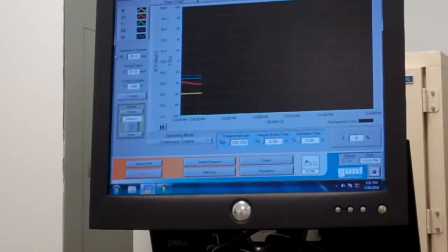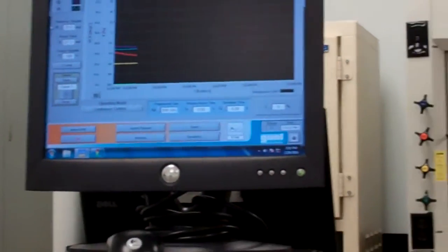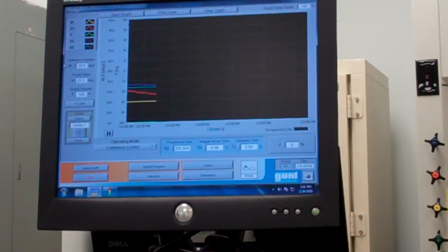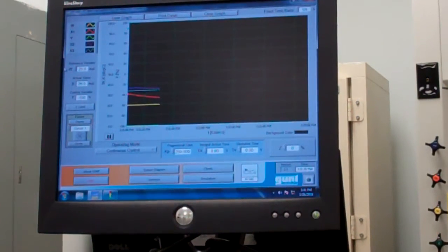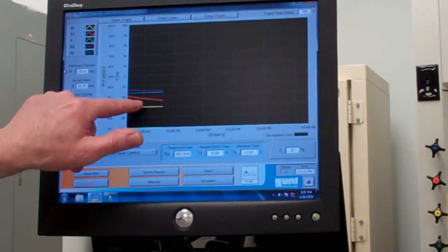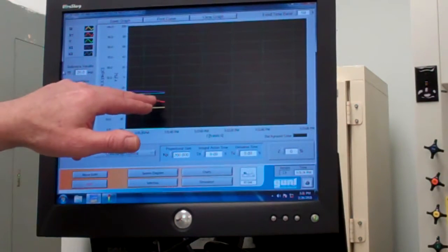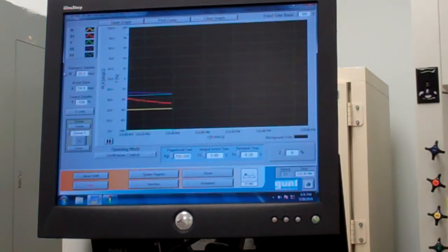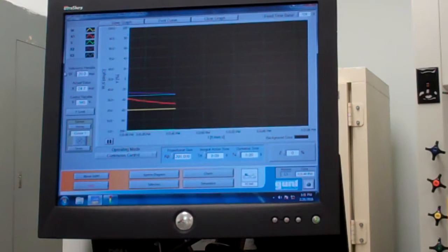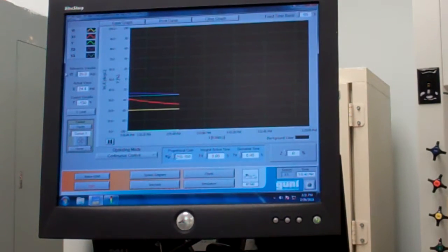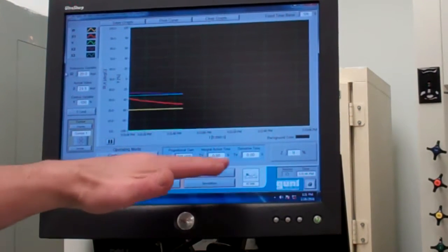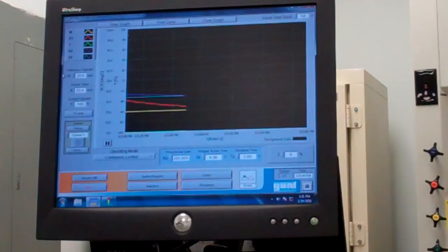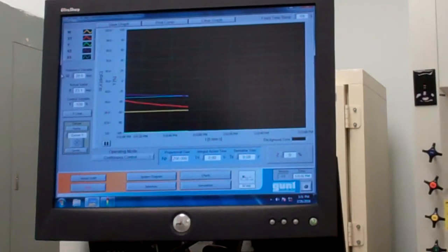And you kind of should already guess that X1 is going to respond much faster since it's closer to the heating element than either X2 or X3. So we're going to focus our primary attention on X1, and so basically when X1 reaches a new steady state, that's when we want you to then introduce the next change and start the next part of the trial. And then eventually what we'll also do is we will change integral settings on here, and you'll see the effects of that. And again, that'll be clear when you look at the